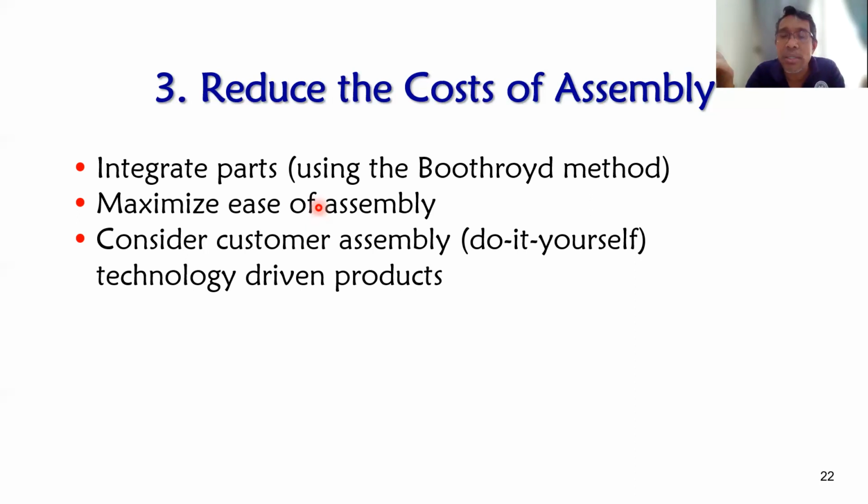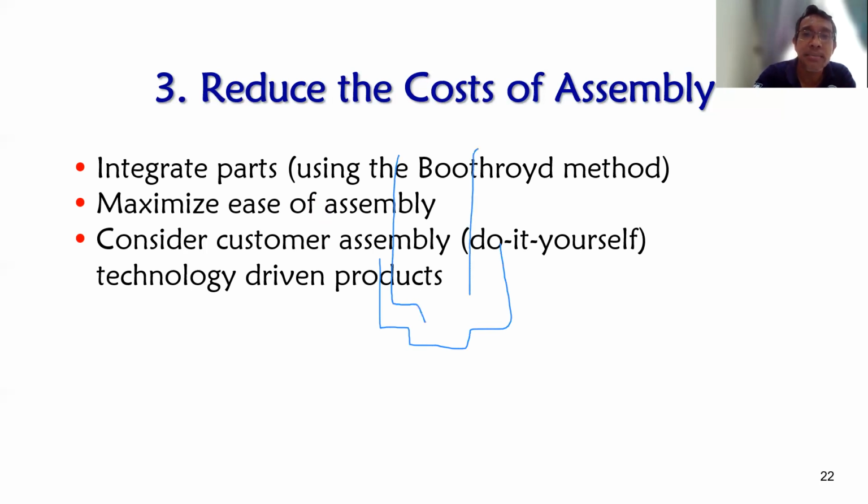So the most common self-alignment feature is the chamfers. When we design the part, for example, when you design the part and then you have another part to put inside this one, for example, like this. So the chamfer here will help you make a size alignment. So normally we will design inside this one a chamfer like this.